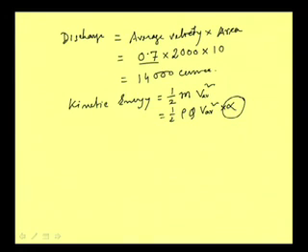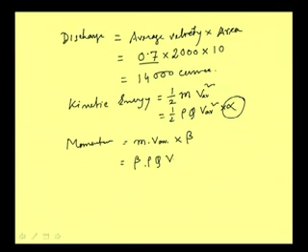Now, our problem is to find out this alpha. Similarly, if we calculate momentum, we can calculate it as mass into average velocity, but in reality this will not be correct. So, we need to multiply it by the coefficient beta. So, we can write beta times mass, which is again rho into q, into V average. That way we have the mass and velocity, and multiplied by beta we can calculate momentum.